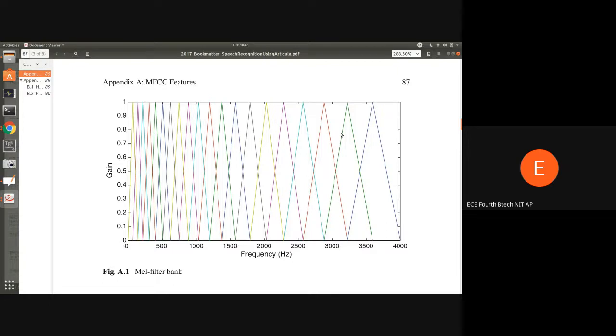Masking subdues the frequencies near it, and this effect of subduing the frequencies near it is stronger as the frequency diverges or is farther away from its focal point. So in a critical band we take a central frequency and then we put a triangular filter on it.